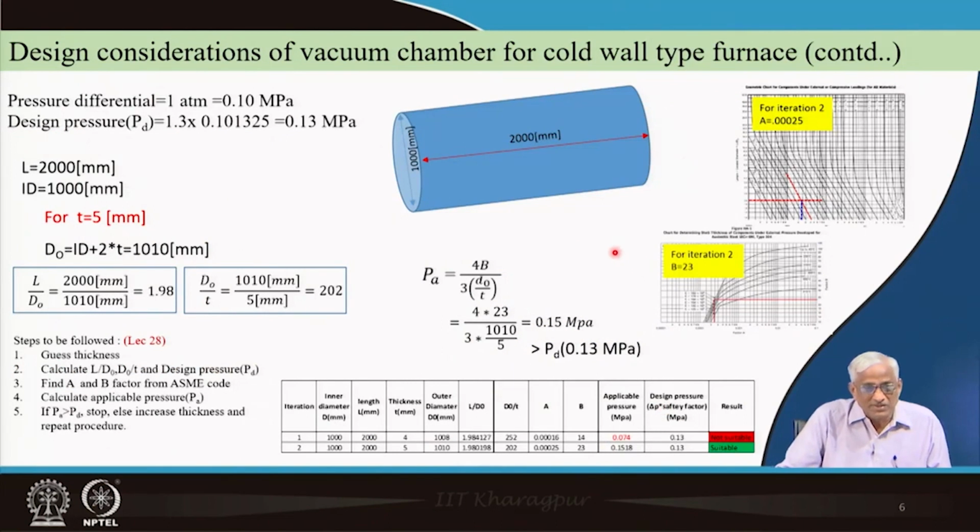So, once you understood the system properly, then once you make this 0.13 megapascal, which you have seen in the 28th lecture, and at that time we took 50 centimeter type, because vacuum furnaces are typically 1 meter diameter and 2 meter long, where you can have a front side quick open door, or there can be bottom or top openings depending on the type, we will see later. Weldings will be there, degassing has to be done, leak testing has to be done.